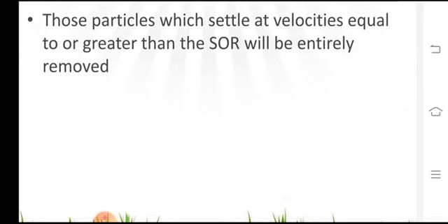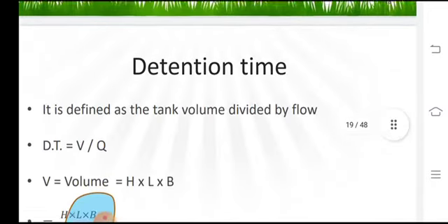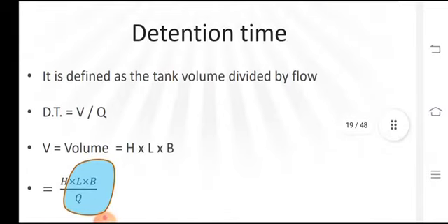So those particles which settle at velocities equal to or greater than the surface overflow rate will be entirely removed.